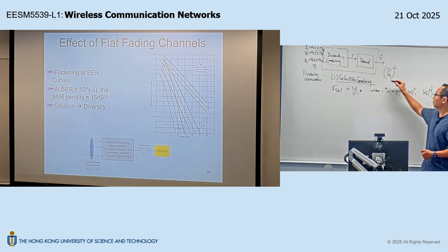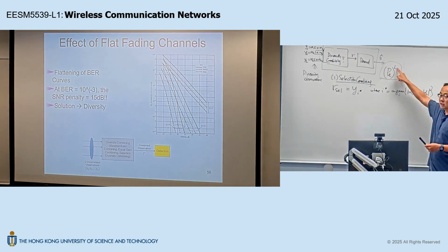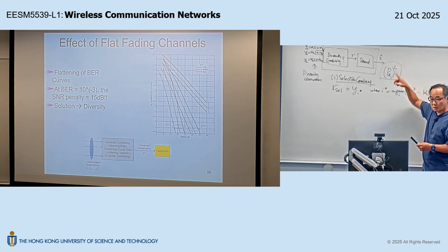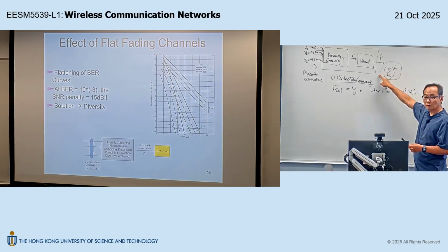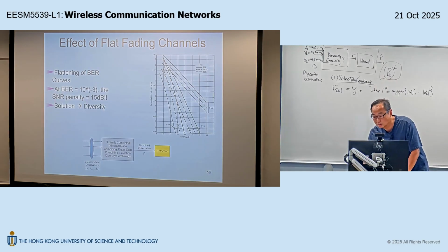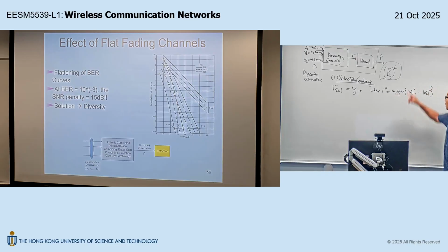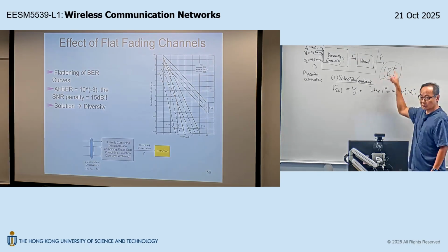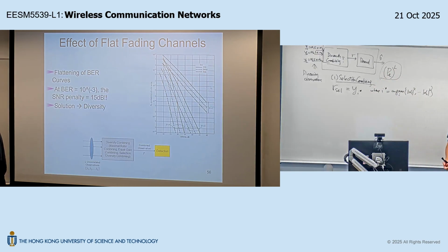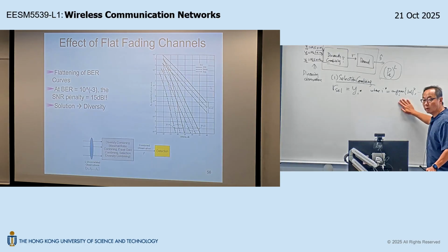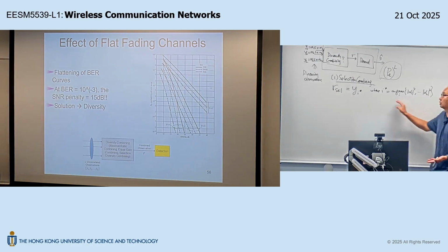Okay, so it's because of this that it gives you the diversity benefit. This is the exponential of L times. So if you take log on both sides, this L becomes a coefficient. That's why, since the y-axis is in log scale, it is log PE. After taking log, your slope is increased by L times. Is that okay? This L, after taking log, becomes the coefficient, and that coefficient becomes the slope of the line, okay? So this is one simple way to combine the diversity observations.